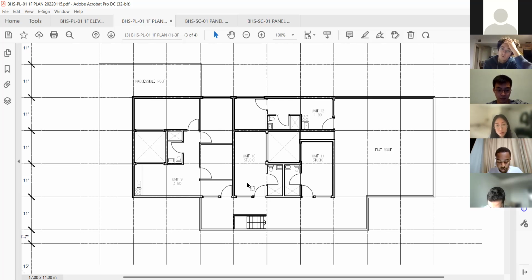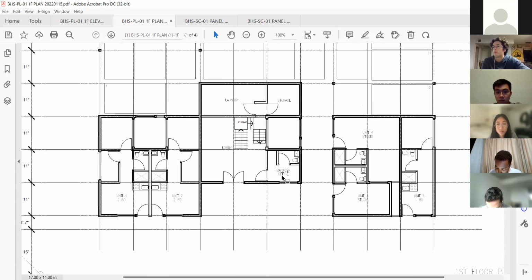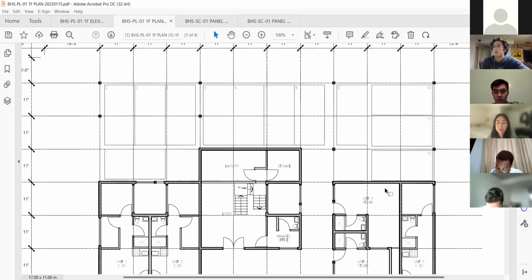My one worry, just looking at the general layout, is that you generally want to have your technical equipment, like the stuff that goes into powering the place, your water heater, some sort of ventilation components, which are all pretty heavy equipment, kept at the ground floor. I've been going back and forth through the plans, and I fear that stuff is not going to be somewhere in a central location on the ground floor.